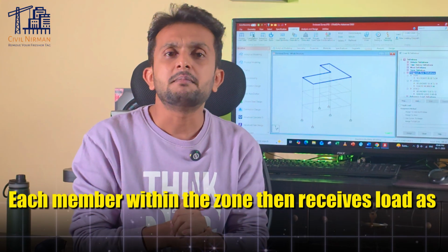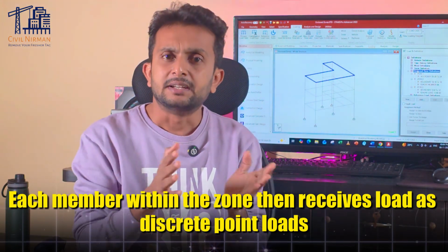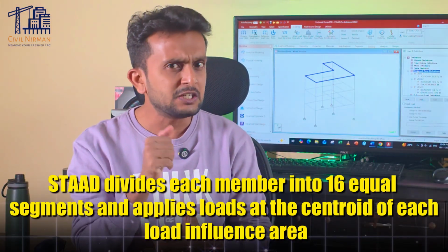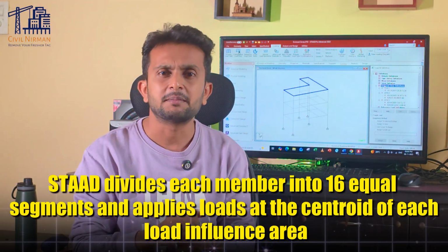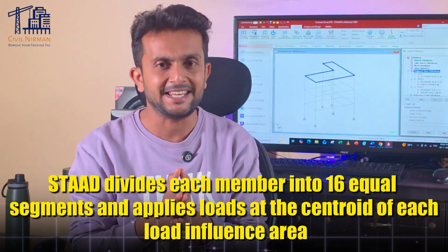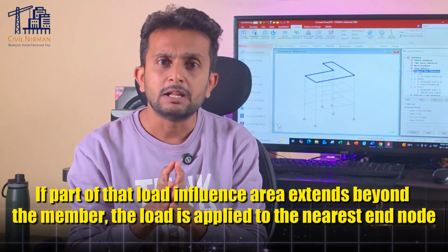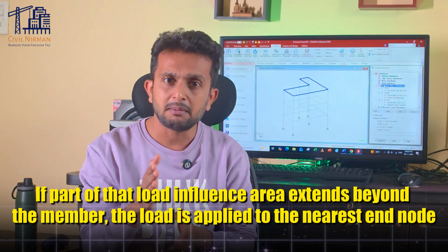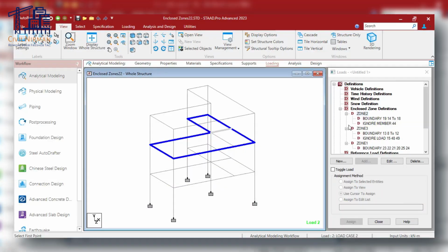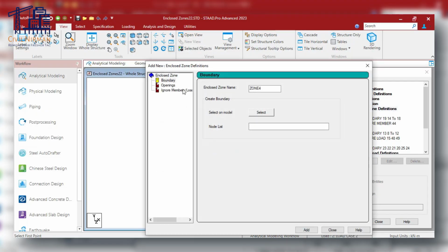Each member within the zone then receives the load as discrete point loads. STAAD divides each member into 16 equal segments and applies loads at the centroid of each load influence area. If part of the load influence area extends beyond the member, the load is applied to the nearest end node. The most important part, members ignored for load transfer.